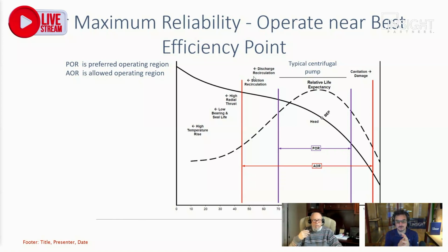So what do you suggest for a designer today? If he needs a pump curve, what do you suggest he asks for? We want best efficiency to the left of the design point, so that pumps are selected for best efficiency to the left side of the curve, where that pump's going to spend most of its life. It's looking at the pump selection and understanding that variable speed range and where that pump's really going to operate, and understanding that the design point is there because we have to meet that.